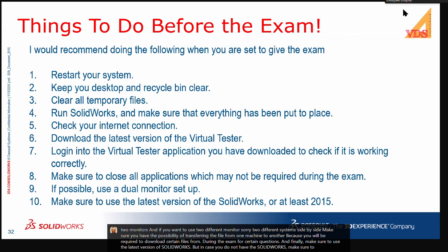Now, what we need to do during the exam, make sure you keep your model simple. That way, if you have to make any changes, you can easily change it. So do not over complicate, like sometimes just to speed up things, people put a lot of features or a lot of sketches into one feature, which makes it overly complex when you have to edit something. Unless you have the design intent clear, I would advise to keep the model simple.